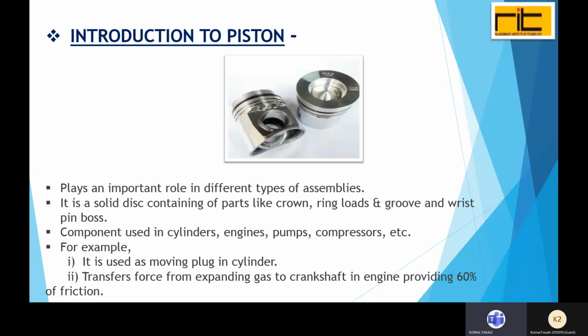The piston is a very important component used in engines, pumps, cylinders, compressors, etc. It is a moving plug in a cylinder which forms the bottom part of a combustion chamber. Its purpose in an engine is to transfer force from the expanding gas to the crankshaft through the connecting rod. We see that the piston plays an important role in many assembly lines, and it is a solid cylinder disc consisting of various parts like crown, ring lands, grooves, skirt, and wrist pin bore.